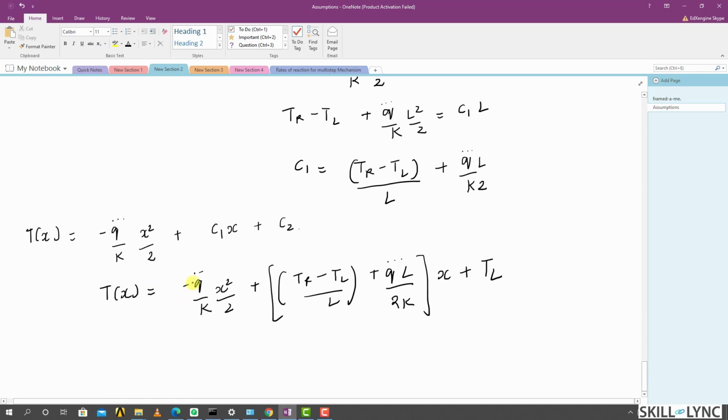Now here is the interesting part. If you assume that this 1D model is for a battery, right? Now again, please remember that for a battery pack, it's better if you derive the equation in cylindrical coordinates. But the idea is, if this equation is valid for a battery pack, you can model Joule's heating, entropic heat generation, aging effects, mixing effects, and you can solve the equation that we had seen in the previous presentation. You will be able to compute q triple dot, and from that you can estimate the temperature within your battery pack.